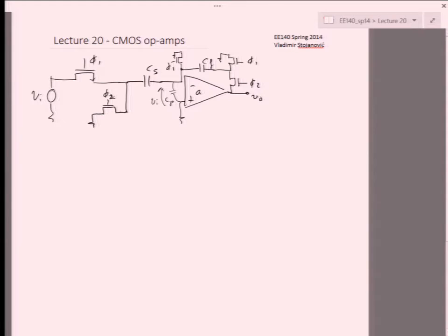So in this case, we're just taking into account a little bit more realism in the sense that there's some parasitic input capacitance into the amplifier. Let's say that's the gate capacitance. It's also some interconnect between the capacitance and the amplifier.